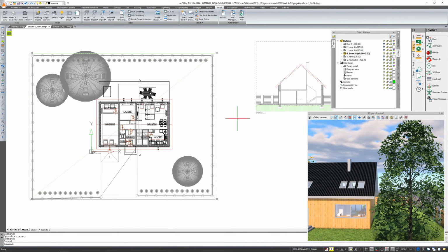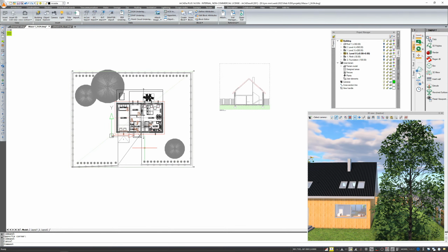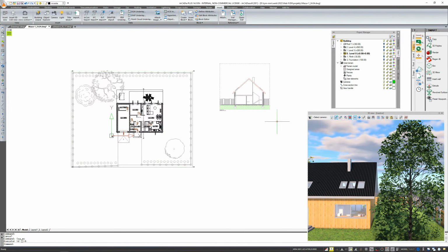You can insert any number of views because at the beginning you draw the building, that is, as it is actually one level above the other or under the other. However, if you want to print it later, you want to show each floor next to each other or below each other. Of course, you can add each next view and you switch to it in a different level. What you can see on the given level, I will show it in this view, but I will delete this 3D CAD view first.